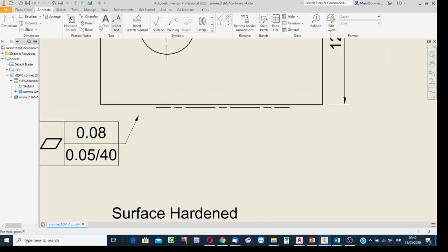And then show the necessary dimensions. For showing the dimensions, select the Annotation tab and click the Dimension button. I started the process. I know that the starting point of the chain line corresponds to the starting boundary of the portion of the surface, 30 millimeters away. Indicate this as a reference, indicate the terminal point, and then move the cursor. Since in sketch mode I located the terminal point 30 millimeters away, of course when I show the dimension it is going to be the same. Then click OK. Indicate the chain line and then move the cursor.